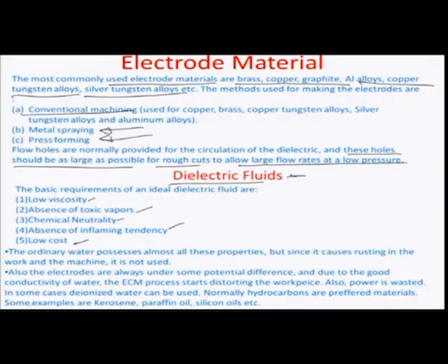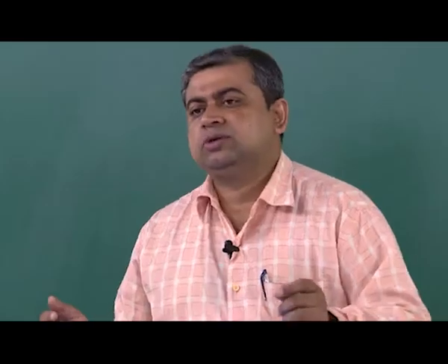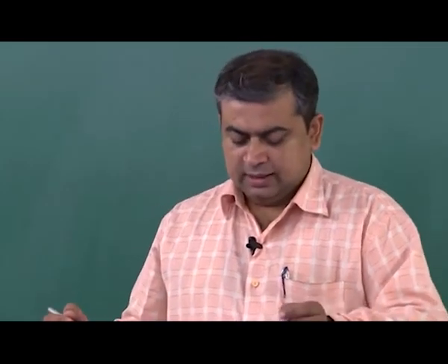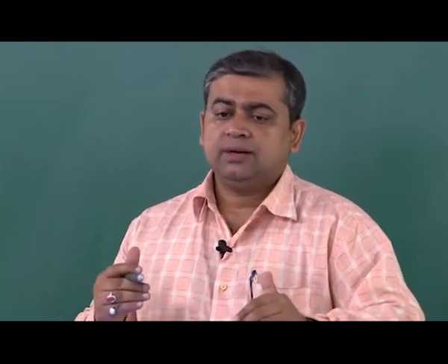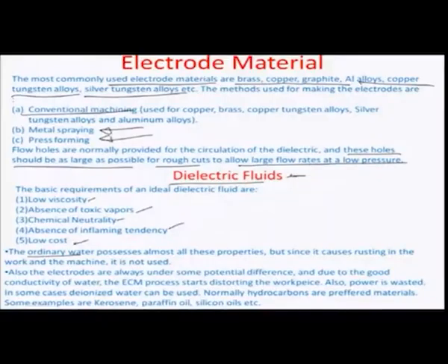Okay. So, typically ordinary water and sometimes mineral oil are used mostly for EDM fluids, and what is also important is that the fluid that you are using should have a relatively higher dielectric constant, so that it can support the respective potential difference between the tool and the workpiece, so that it can lead to a sparking condition. So, with this I think the EDM section is more or less covered.